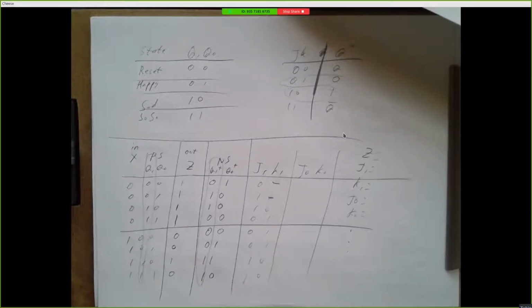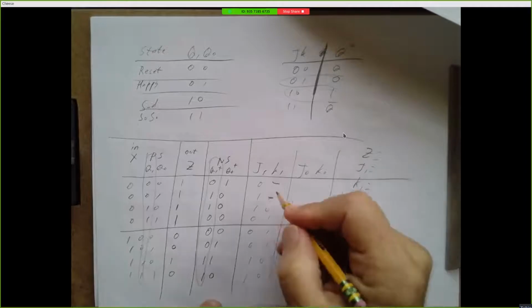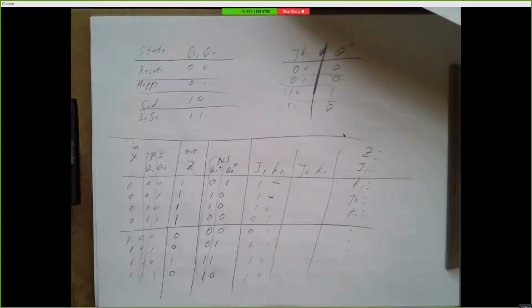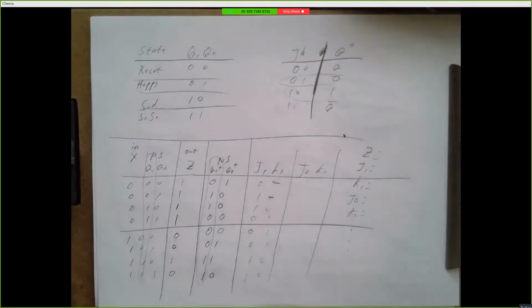And how do you do that? Well, you can do a straight sum of products, but since you have don't cares, and you're going to have 4 don't cares in every column, you can take advantage of those in K-maps, because in a K-map, you're allowed to cover a dash, you're not required to. So you use the dashes where it helps you get larger rectangles or fewer rectangles, and you ignore them otherwise.